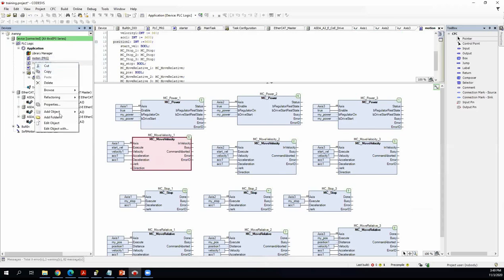Under the ST language, you can create an action or method or property. These are object-oriented tools, let's say. CODESYS allows you to program motion control in an object-oriented way. So you can also use ST language for machine state control, and for the motion you can use CFC, for instance. For the MC power, when it is needed you will call it, otherwise you will not call it.